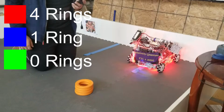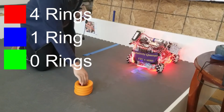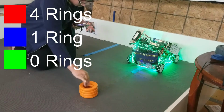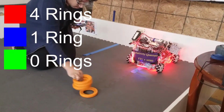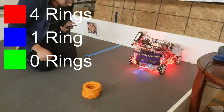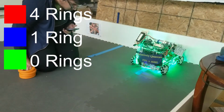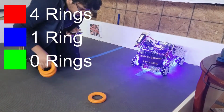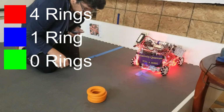One thing we knew would be imperative to a successful autonomous this year was detecting how many rings were stacked. Initially, like most teams, we started by using the sample code provided by FIRST that had a pre-trained machine learning algorithm that utilized the TensorFlow library. However, we found that although it was good at detecting whether there was a ring or not, it could almost never tell the difference between a stack with only one ring and a stack with 4 rings. So we added a custom touch to the program.